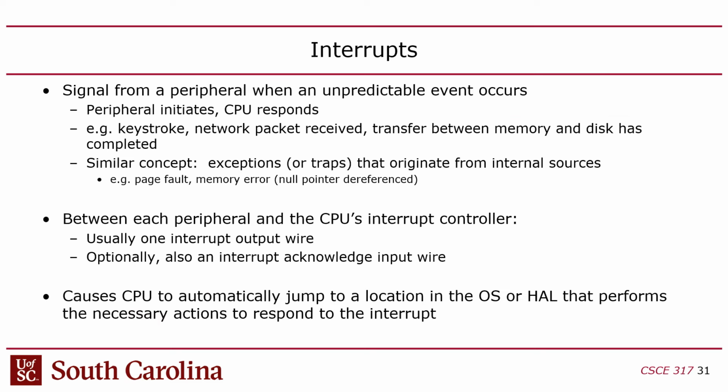Okay, so switching topics again, interrupts. I mentioned interrupts briefly. Interrupts are, as I mentioned, a signal that's sent from a peripheral to the CPU. It's the only way a peripheral can really initiate communication with a CPU. Because otherwise, generally speaking, in a computer, the CPU is always the master. It controls everything. And if you have an accelerator, like a GPU or a TPU or a neural processor, those are all essentially peripherals too.